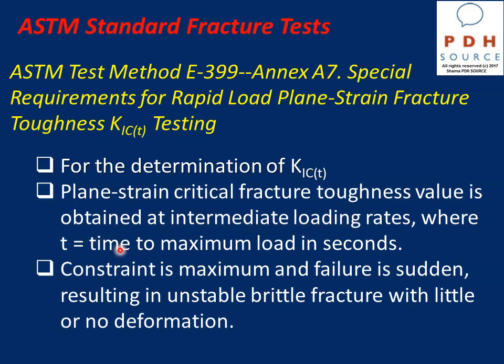So T is about 1 second. The time to the maximum load is about 1 second. So this is to determine K1C. So this is dynamic under intermediate loading. Again here, constraint is maximum and failure is sudden, resulting in unstable brittle fracture with little or no deformation.